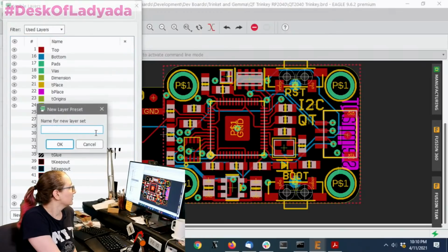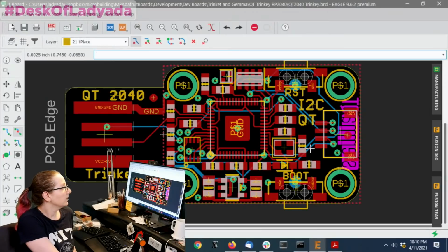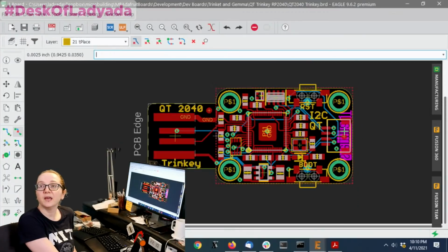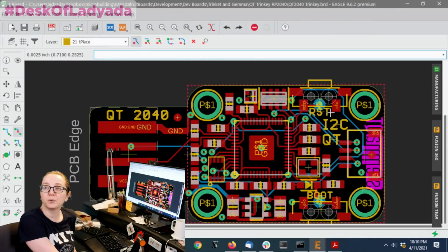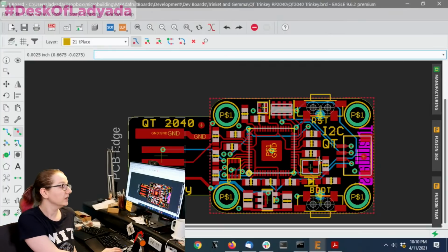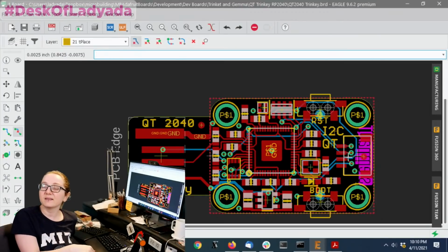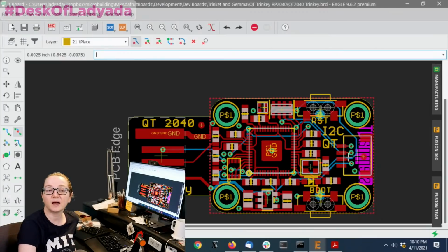So this is an RP2040 with a STEMMA QT port on the end, and it plugs into USB. It's the same size as our standard STEMMA QT, like 1 inch by 0.7 inch. So you could just pop the sensor on top and attach it somehow, using the 4 mounting holes. It doesn't make sense for every device, but let's say you wanted a gas sensor. You would take an SGP40, plug this in, and then you could get data out.